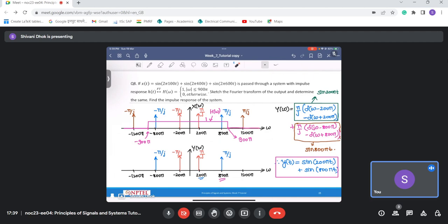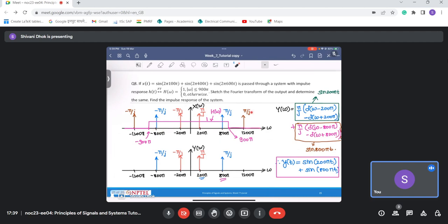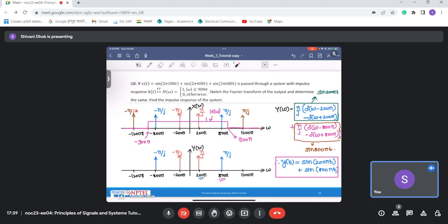That is, suppose this is the range of frequency that I actually want in my signal, which I need to transmit or just process afterwards, and these are the frequencies that I don't want, so I can just reject those by designing appropriate filters. And this visualization of what kind of frequencies I want, what I don't need, can be better interpreted when I go to frequency domain compared to the time domain interpretation. This you can't understand from this.